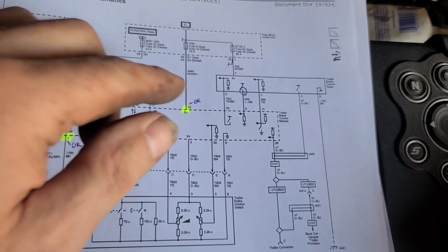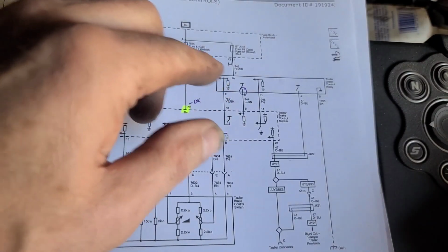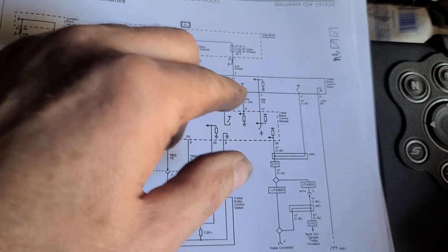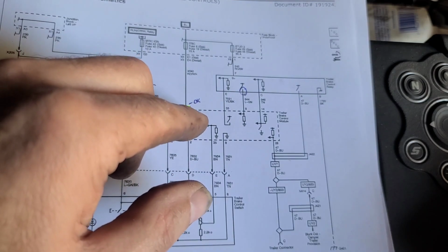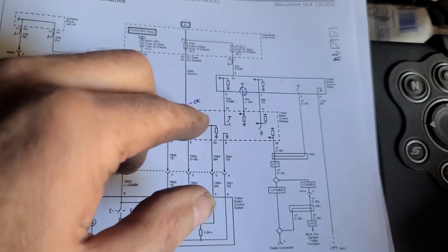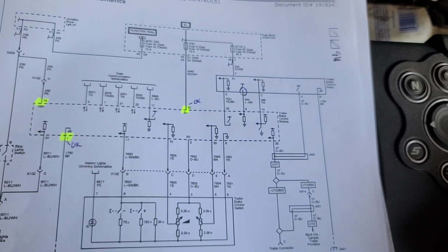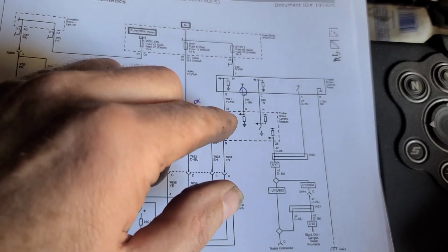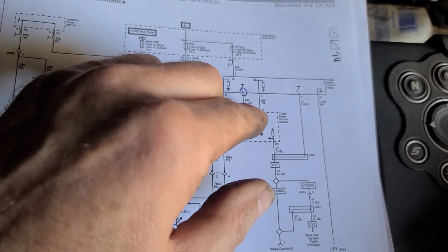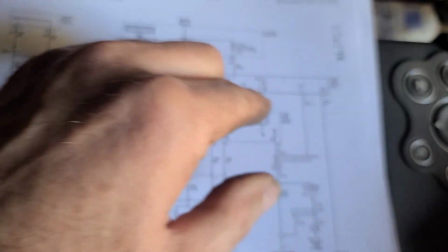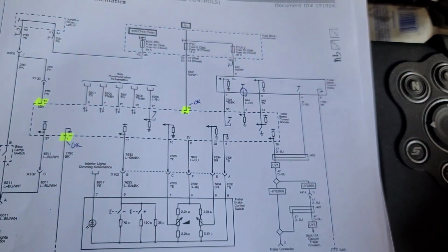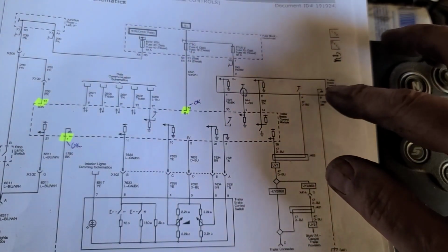I wonder if I should put an ohmmeter between, disconnect the trailer brake control relay and disconnect the trailer brake control module and qualify the wires. Or just disconnect the trailer brake control module and I shouldn't have any voltage present on any of these 3 wires. Any of the 4 wires should just have voltage present on